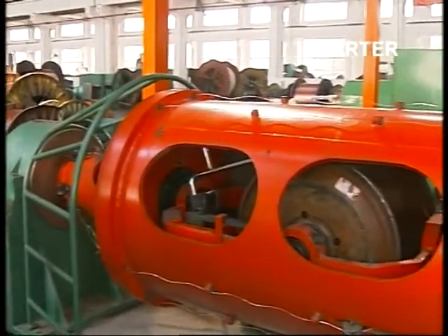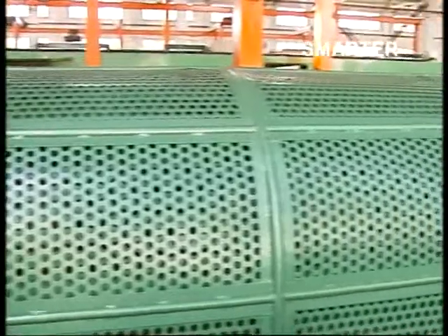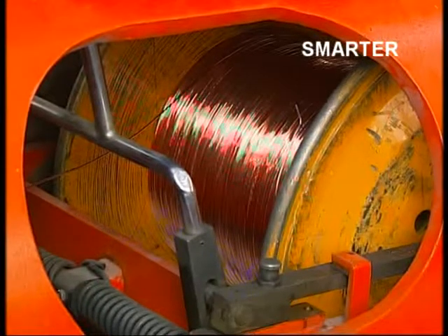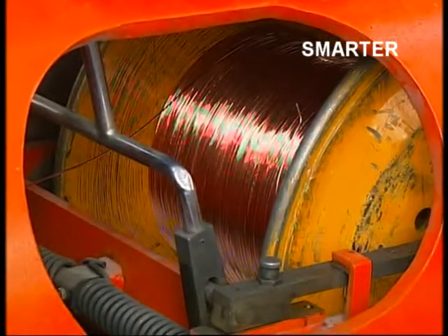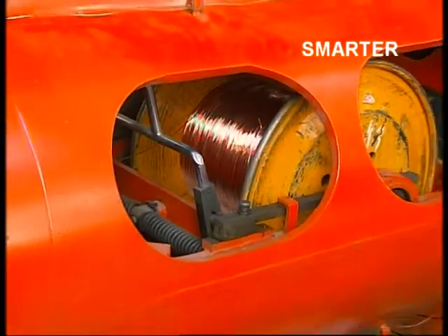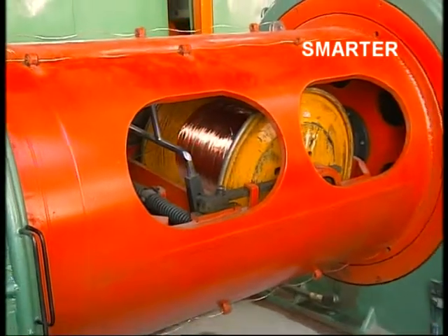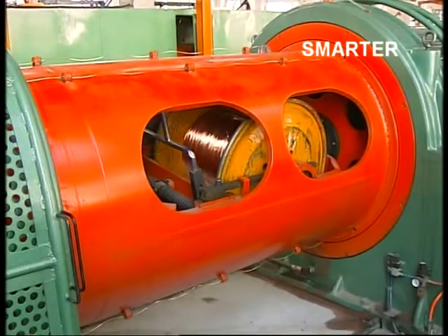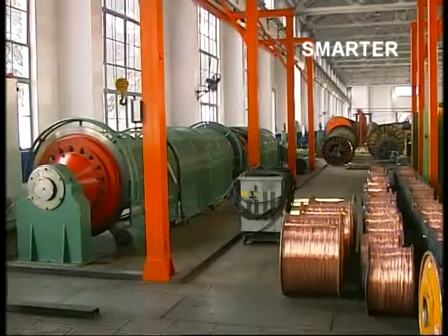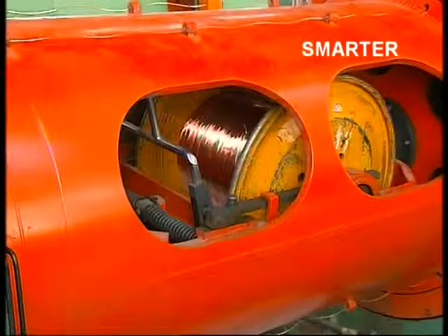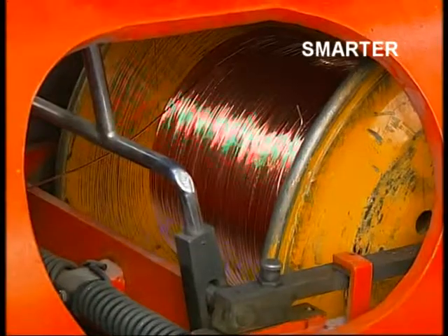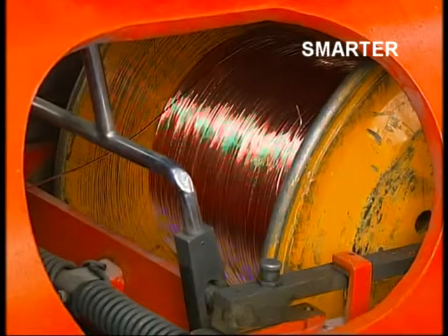The 6-bobbin cage consists of front rail bearing seat, middle bearing seat, cage, cradle, braking stand, and rotary head, etc. Now, we are the only company in China that uses a big bearing for supporting the middle of the cage. The cage is supported by a complete bearing with features of high speed, low noise, and easy maintenance. The big bearing in the middle is continuously lubricated through a thin oil tank. The bobbin in the cradle is loaded with a shaft.